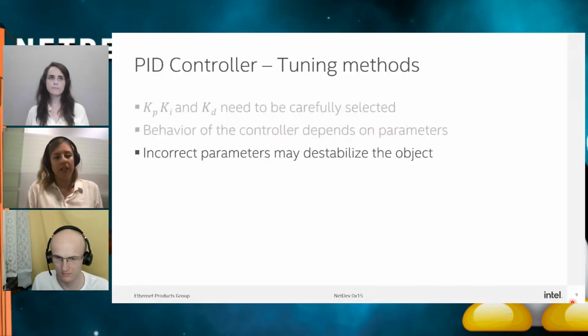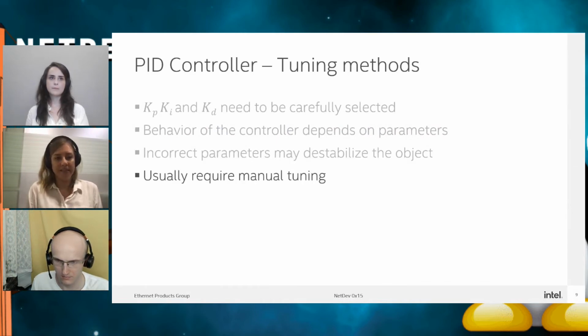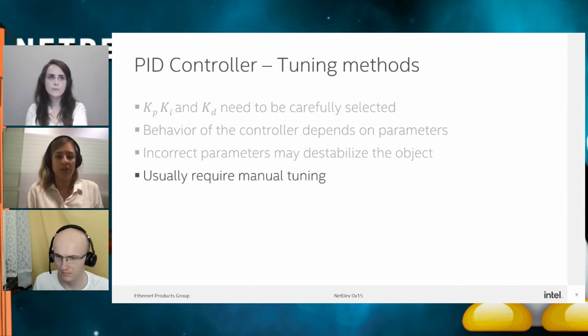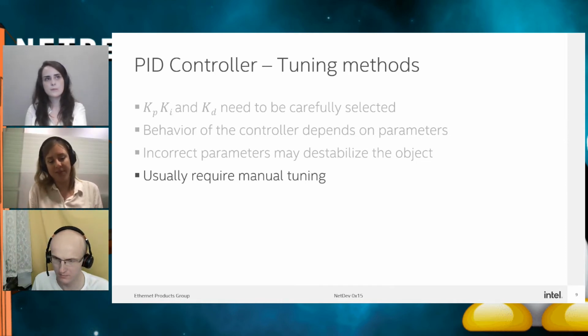What is interesting, engineers working with control systems usually decide to tune PIDs manually or leave them with standard settings. There was a research, control loop testing, that indicated that 75% of PID-based loops are out of tune. And this can also apply to the Linux PTP implementation, as we use default P and I values. And nowadays, we do it.